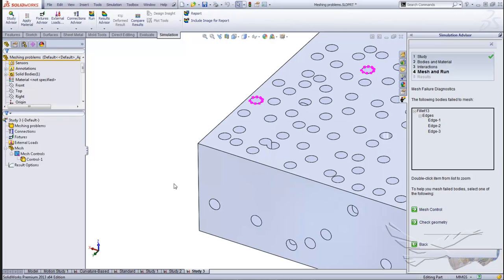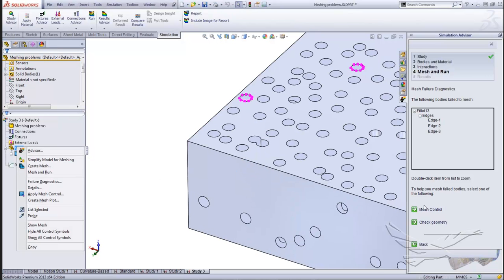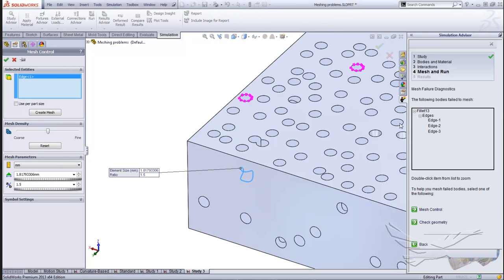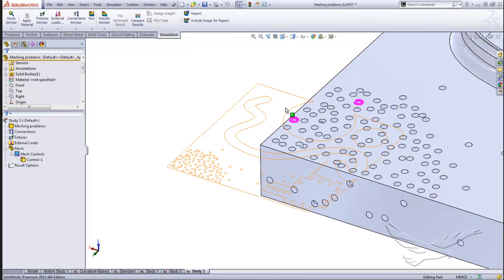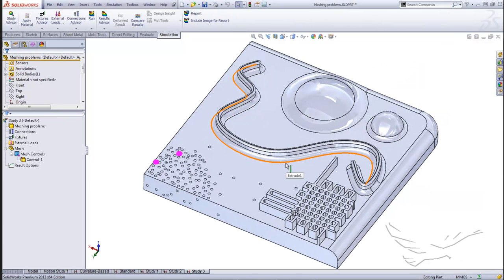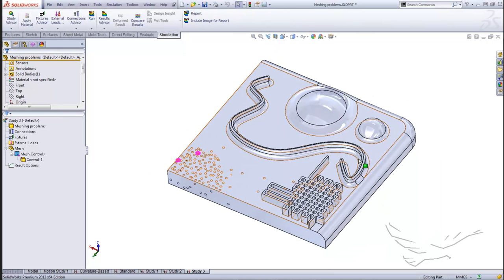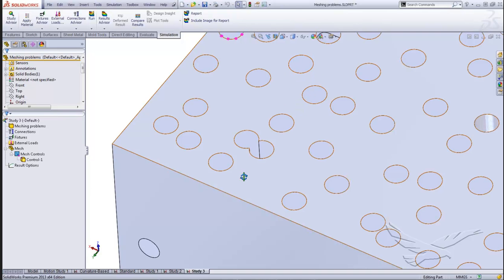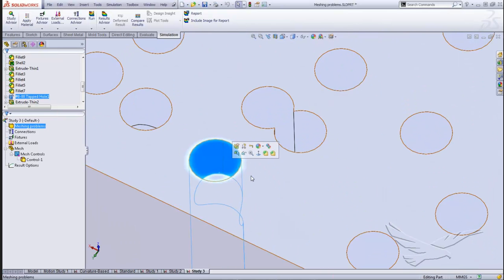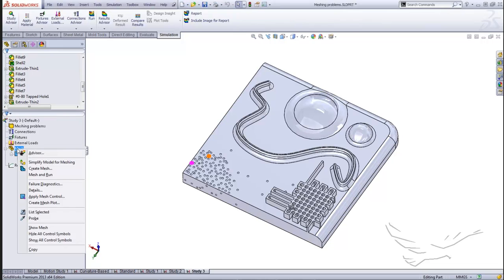And generally, when you apply mesh control to the same edges, you'll see a warning that says, hey, there's a mesh control already applied to this edge. The smallest mesh control will be applied. But I could interpret this a couple of different ways. For example, I could interpret it as a way of saying, okay, I do need a smaller element size on those 3 edges particularly, or the global element size is having a hard time transitioning to these smaller element sizes on these edges.